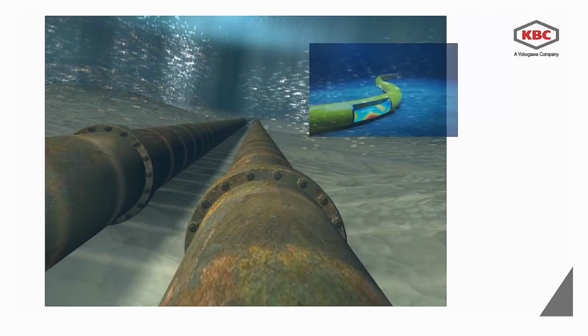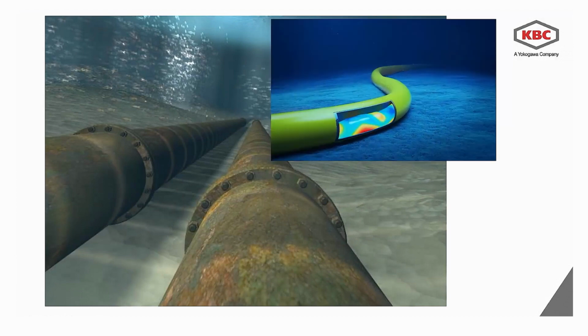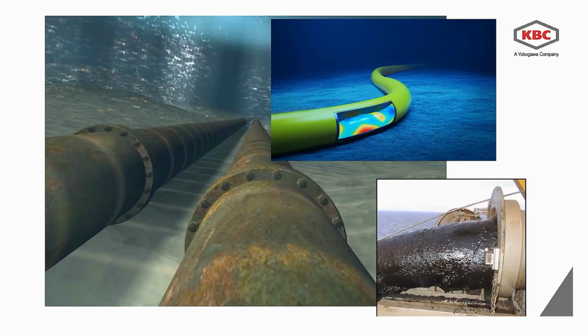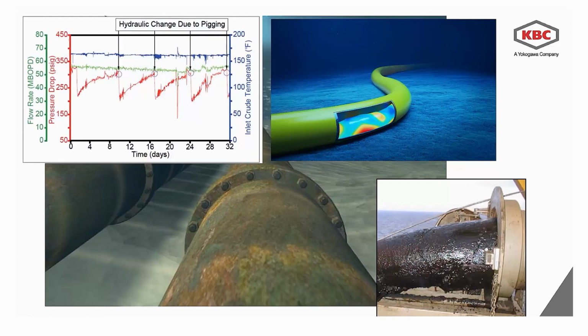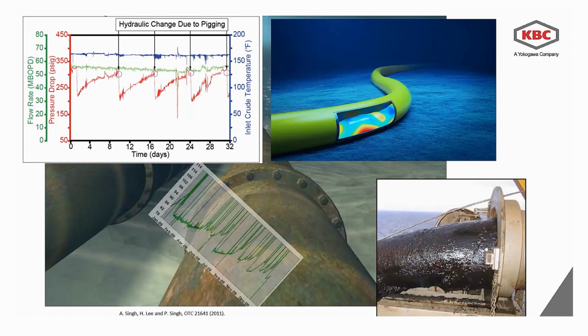An increase in the pressure drop between the inlet and outlet of the flow line is an indicator of wax deposit buildup in producing assets. Since operators often control pressure at the outlet, the buildup often increases the pressure at the inlet as the deposit progressively obstructs the flow.